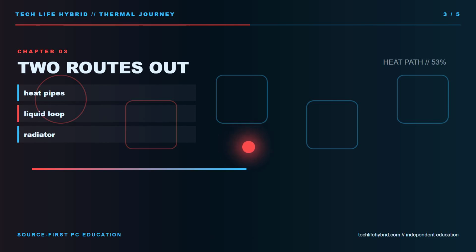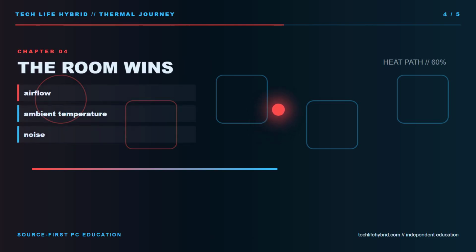This is why isolated temperature screenshots are weak evidence. Compare the same hardware, room conditions, workload, duration, settings, and measurement method. Watch temperature together with clock speed, power, noise, and completed performance. A processor running warm while holding its intended clocks may be behaving normally. A machine that gets hotter, loses clocks, and slows during a repeatable task may have a cooling limit worth investigating.